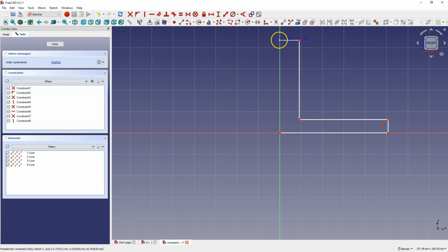And here, similarly, hover over the y-axis. As it is highlighted in yellow, click so that this point is connected with the y-axis, and now hover over this point. When it's highlighted, click. And now right-click to finish drawing the polyline, and right-click again to cancel this command. Now this line should be a horizontal line, so select this line and select Constrain horizontally. This line is vertical, so it's okay.